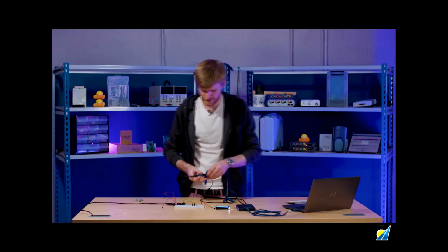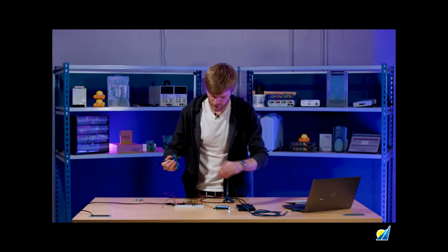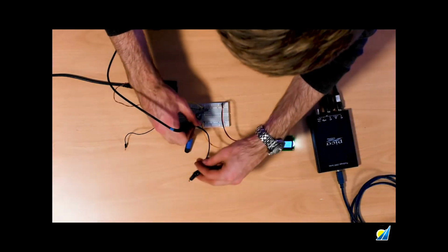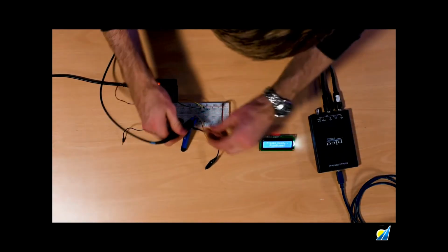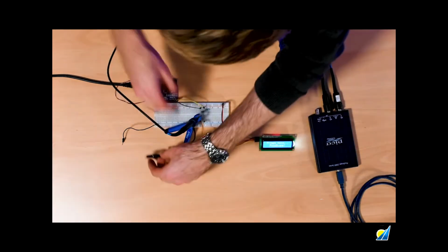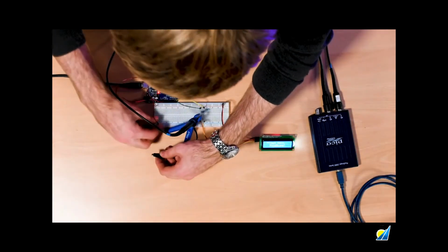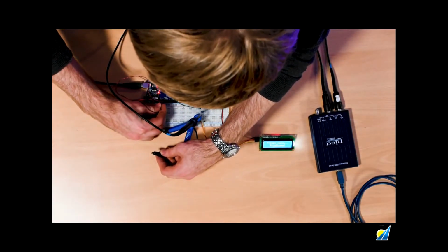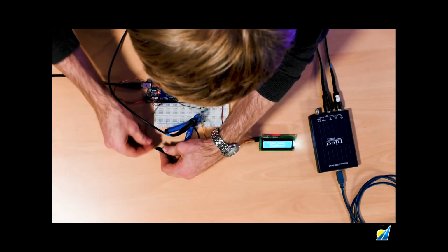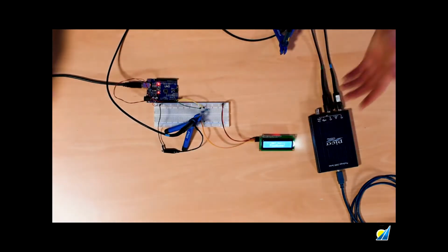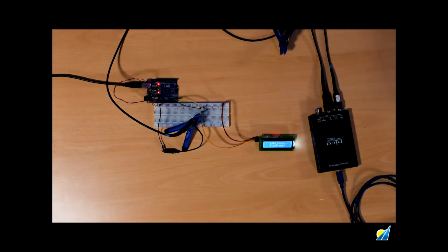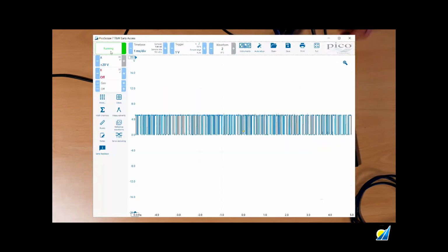Right. So what we're going to do is put channel A on the SDA line, like so, and then ground it. Make sure to ground your oscilloscope probe. Beautiful, still doing the same thing. Let's play. There we go, that's beautiful.